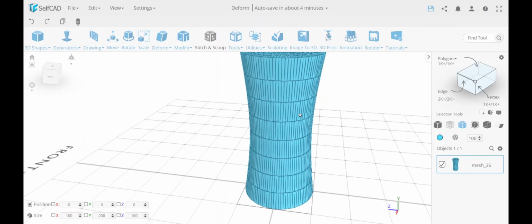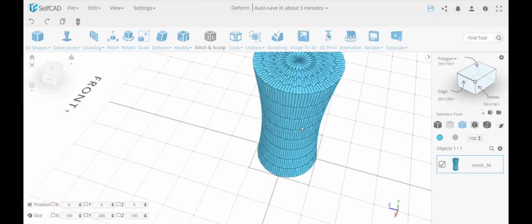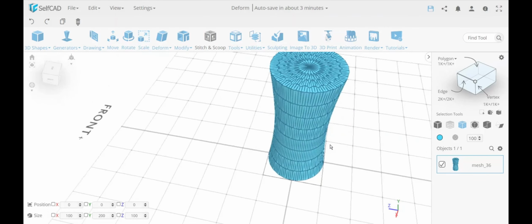And there's different ways to do it. If you think about the resolution that I've shown before, the resolution tool is using something that's called tessellation. It's a different approach. Actually, advanced resolution has additional options, a lot of different algorithms for how to solve that problem. In a subdivision modifier, what they do is they split every face equally throughout the entire object. And basically, you see all of these faces are split regardless of whether they're being rounded. Otherwise, they will create non-manifold meshes.